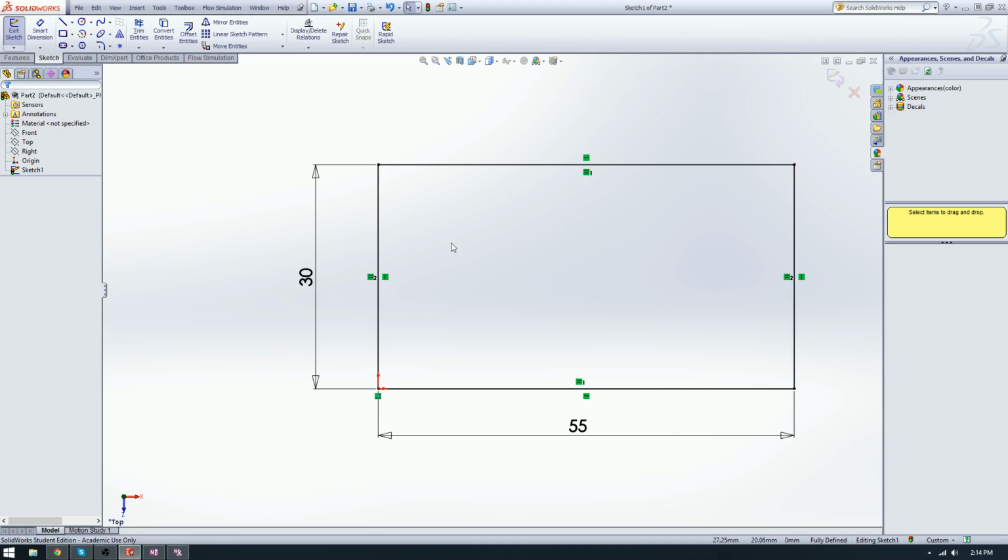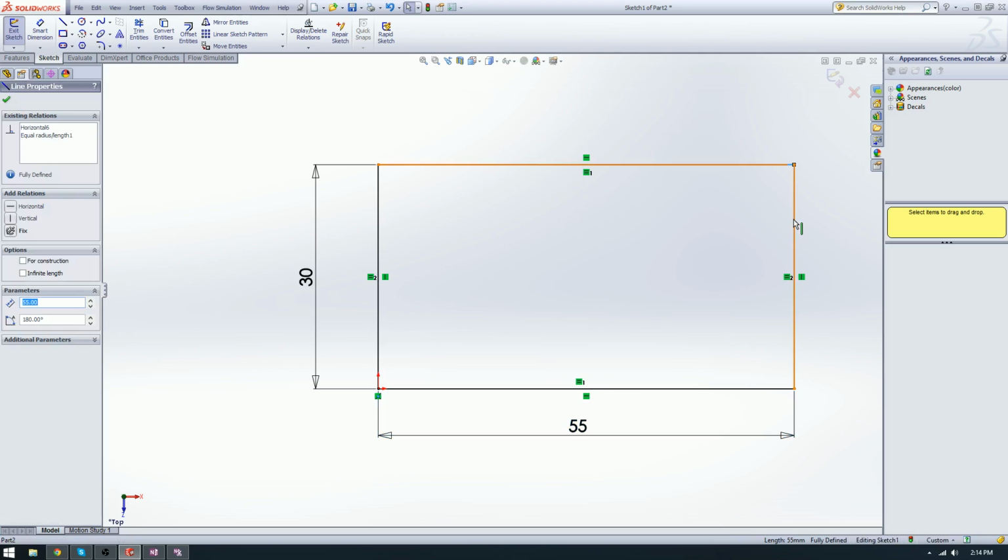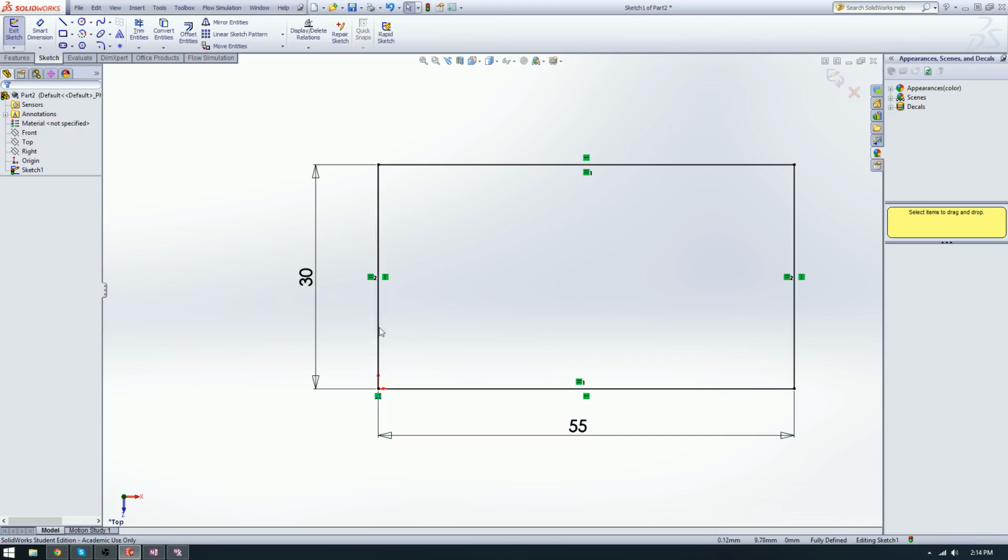And each line had a corresponding equal line. So nothing could move. Now what we've done is we've given SolidWorks a point of origin and a distance on both the X and the Y, which essentially gives these a distance as well. All of it emanating from the origin, so SolidWorks now knows a starting position and a distance for everything in the sketch.